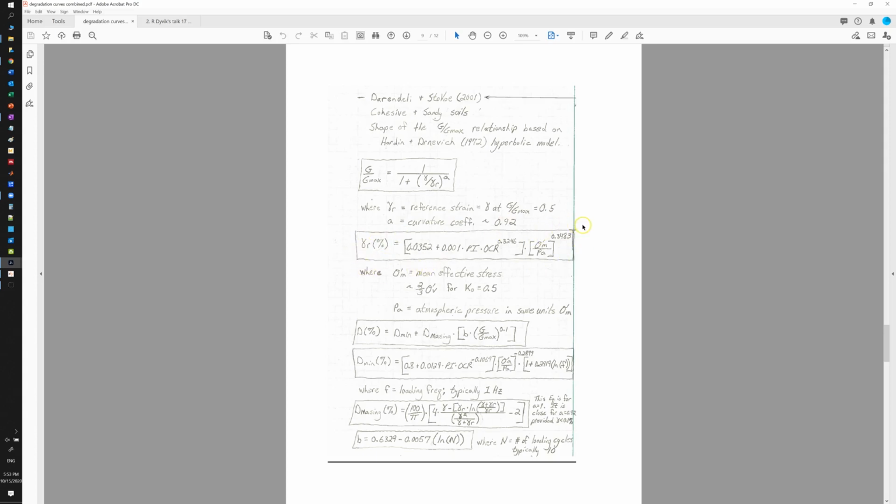axial strain for the curve. So actually the reference strain, sorry. So this Gmax equation also depends on this reference strain. So this is the G, right? This is the G that you want to have at the end of the day, and this is the y-axis, and this is the shear strain, the x-axis. And Gmax, you get this from the field. So this is a field measurement. I'm sorry, I have a hard time, but you understand this.